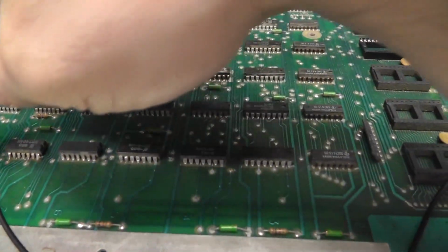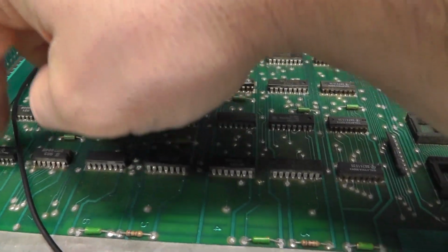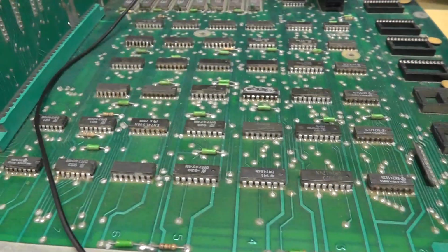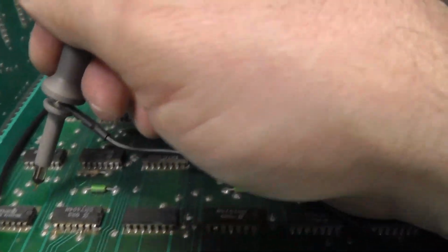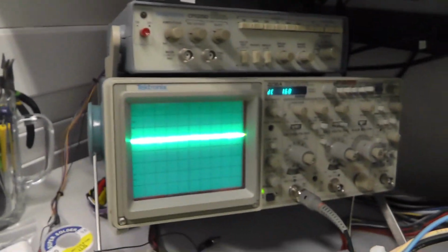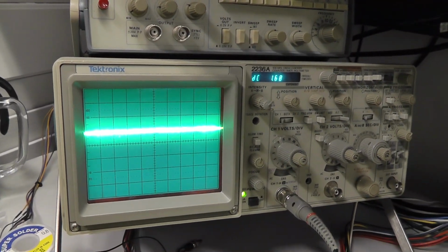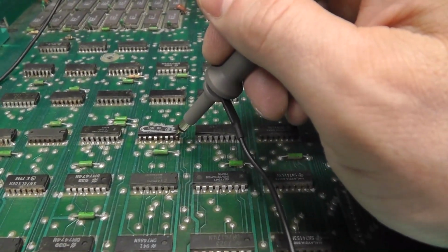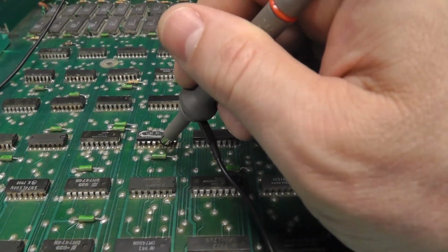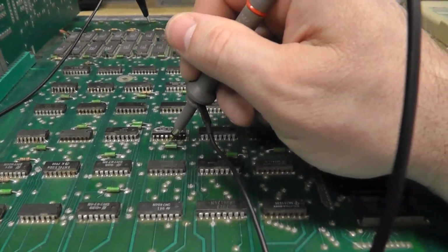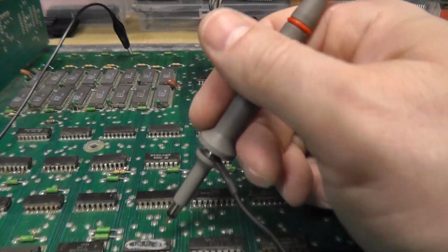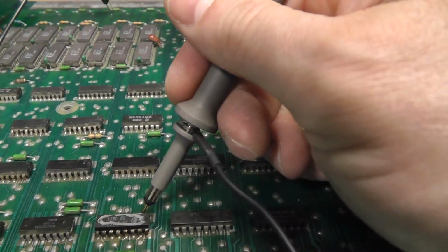Okay, so the inputs to this 7432, or at least the one I'm concerned about, which is pin 1. Let me review. It's pin 1, and that's the voltage I'm getting. Just barely. It's not doing anything except for maybe 1.68 volts. And that goes to pin 13, which is right there. And that is C4. And there's a whole bunch of RAM data inputs coming into this thing. Like, I know you can barely, no, you can't see that. Let me zoom up here.